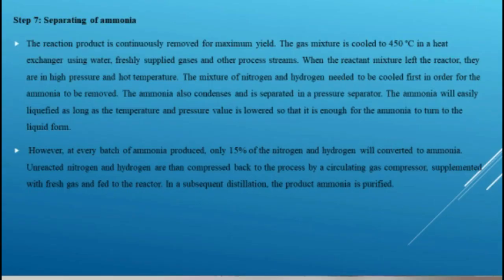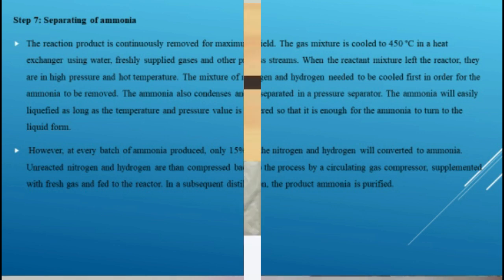For the last step, this is where the ammonia is collected. The gas mixture will be cooled down first before the ammonia is removed. Ammonia will condense and be easily liquefied if the temperature and the pressure are low enough for the ammonia to turn into the liquid form.